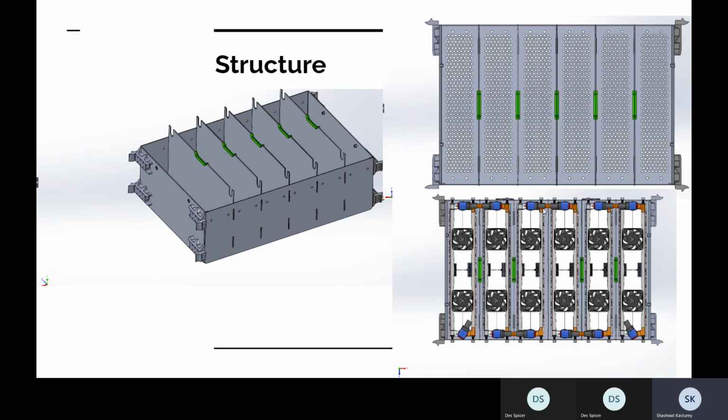More view of the structure here. This is a much better view, honestly. So this shows you the shell of the accumulator. Again, all 90 thou, 60 thou or 90 thou? Yeah, all 90 thou aluminum, tab slotted together and socketed together and then welded up to these separator plates. There are 5 total, as I said before, we have 6 compartments. This construction was the easiest way to arrange 6 modules abreast.